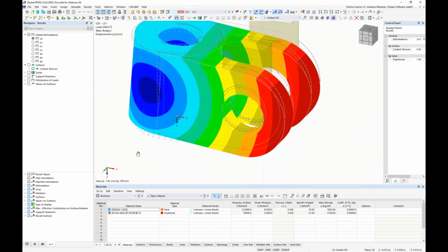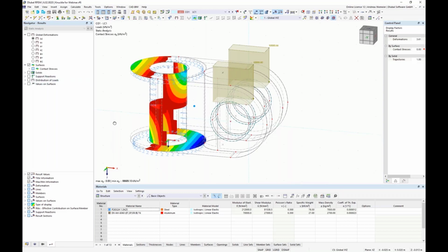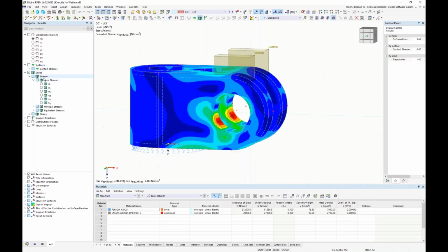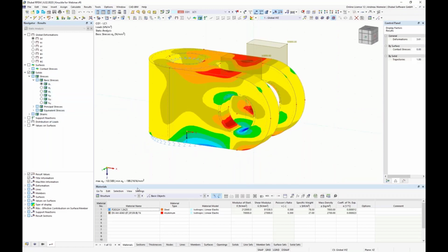What is clear? And for checking loading boundary conditions, you will see you get the restrainment for the top surfaces, pressure here, and in the inside, in the bearing, you get also pressure vice versa, transporting a bending moment. So far, it's reacting fine, and it will give you, let's say, stresses in X, in Y, and Z directions. You get extreme stresses, what is interesting for design, and you get also here strains.